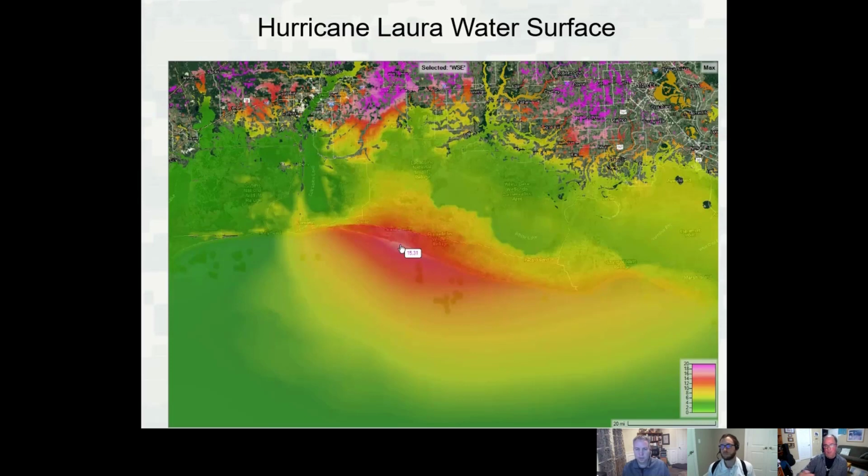Okay. Yeah. And where that line is depends upon what you want to do for the modeling. So in this case, I'm showing RAS out in the ocean, but probably more often than not, you'd have ADCIRC for the ocean, and then marry the two up at the coast, okay, or even inside the coast, and let ADCIRC give you the results to the coast. But just showing, RAS is accounting for the wind forces, and you can do stuff like this right in RAS, at least on a limited basis, accounting for the wind force terms part of this.